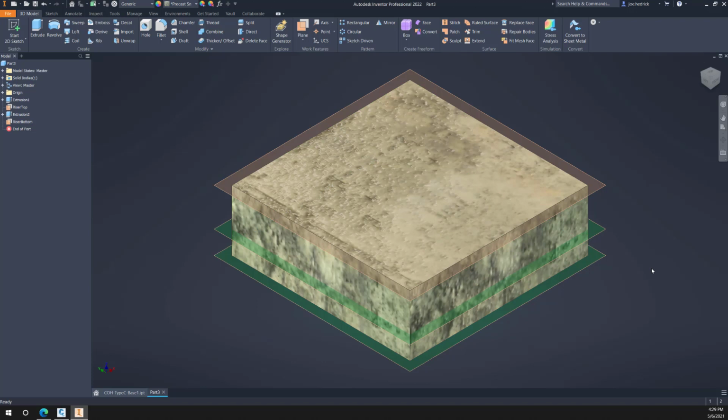All right, so next thing we need to do is let's do kind of a fillet across the top, you know, for the little rounded edge. So that's pretty easily done with the fillet command. And we'll pick that edge right there. We're going to tell it that, you know what, we can just hard code this one. There's no reason to have variables there.